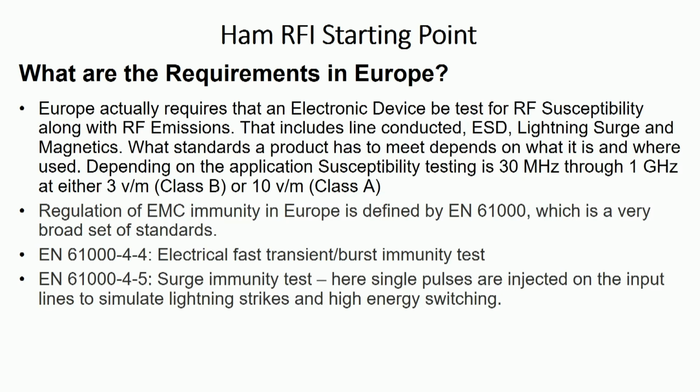Okay, so Europe has requirements for RF, not only the emissions like the FCC does, they also have RF susceptibility. You have to actually take products into anechoic chambers and test them to make sure they don't respond to RF fields. You have to test them for ESD. You have to test them for lightning, surge, and magnetics. So anything that's truly being sold in Europe is probably pretty good RF-wise.